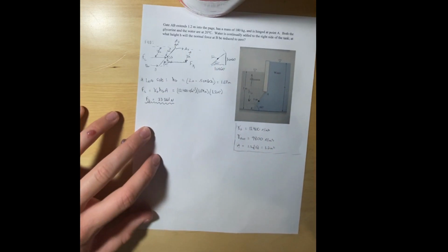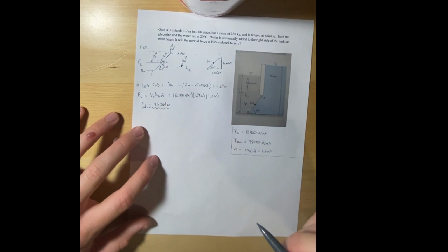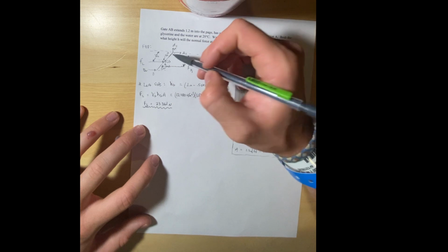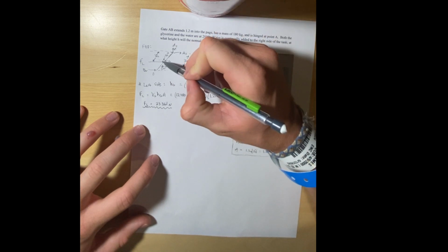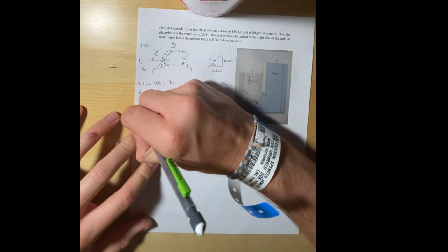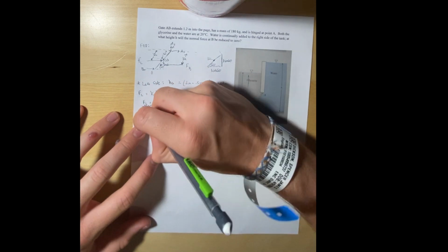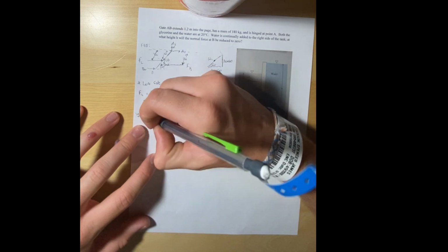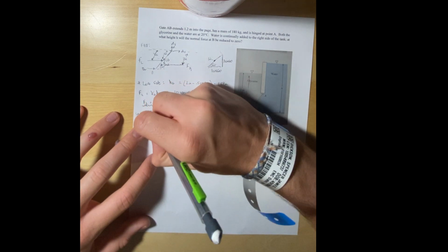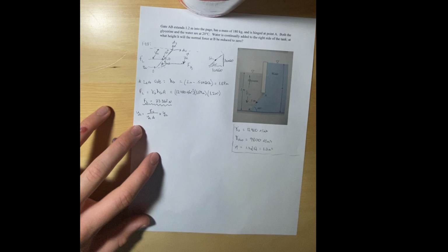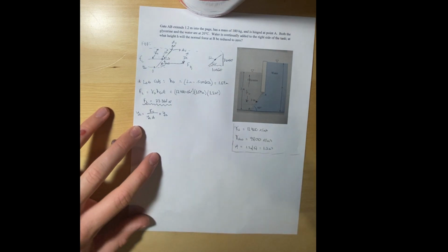All right, now that we have the force, we need to go ahead and find the y sub L term right there. And so that's the distance acting on the force, not this hg term. This is the distance from the A to the force vector acting on that. So in order to find that, this is the equation we use. It's going to be I sub c, just the moment of inertia, over y sub c times A plus our y sub c term.